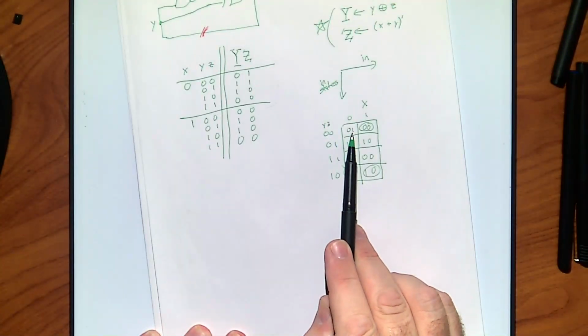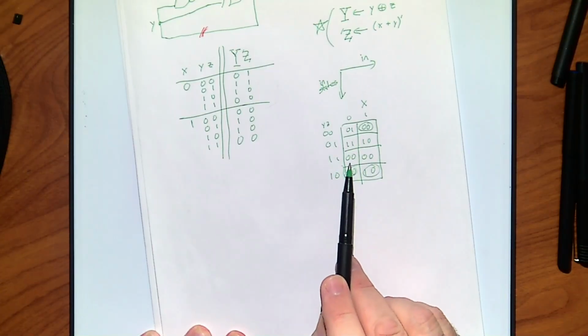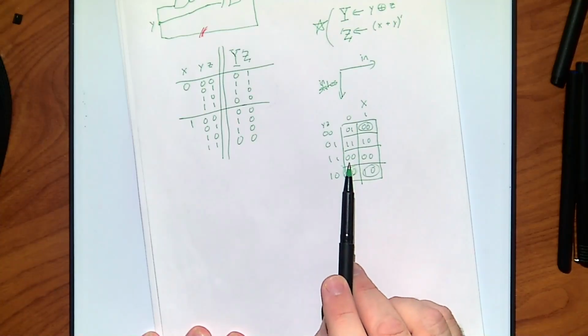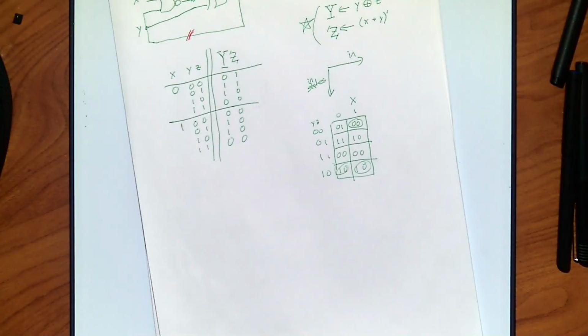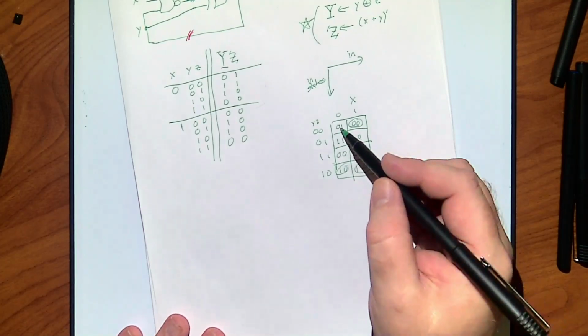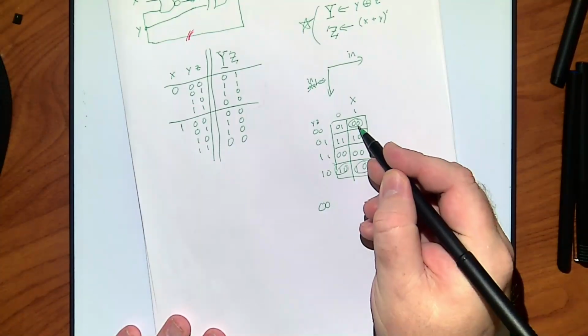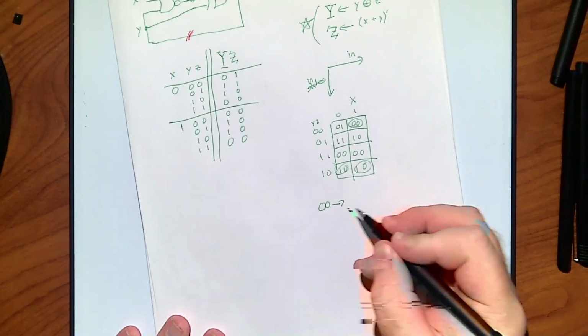If we look at this first column, what's going on? 0, 0 goes to, 0, 1 goes to, 1, 1 goes to, right? And so what is this doing? It's a cycle, but it's a cycle with a race. Right? 1, 1 goes to 0, 0. So it's almost like you've got this spot when you're starting out, assuming I started at 0, 0, which I could, because I could be here and I get x goes to 0. The race is on.